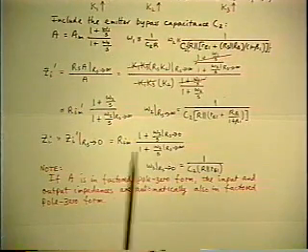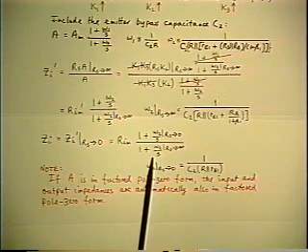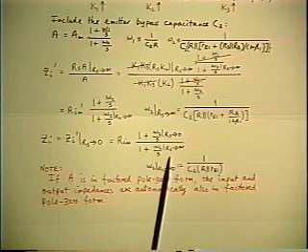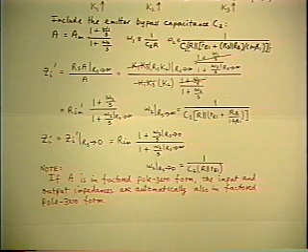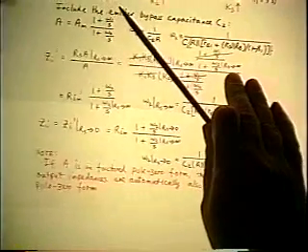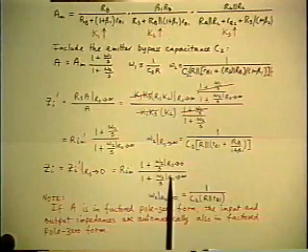So you again get it automatically in factored pole-zero form by using the other version of the theorem. Now notice what would have happened, just to look at an alternative. Suppose we'd had only the theorem for the inside output impedance. Then we could have derived this one directly.